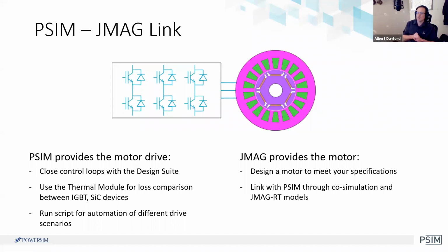So you could say, okay, I want to compare these 3 devices and I want to run this script. And then at the end of it, I want to compare the switching losses on them or what my junction temperature gets to if my heatsink stays the same, those sorts of things. Or, run it at different DC bus voltages, see what kind of torque profile you get, speed torque profile you get when you switch to field weakening during acceleration, all that kind of thing.